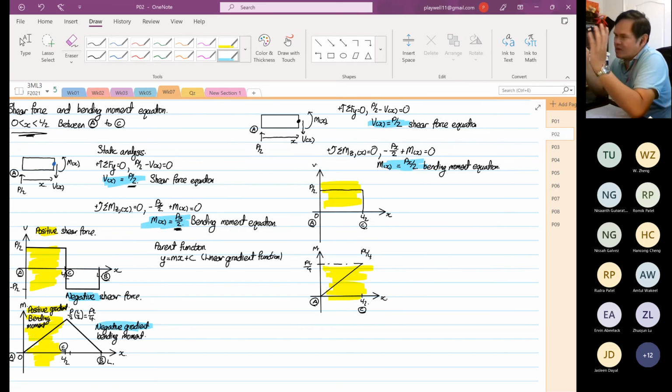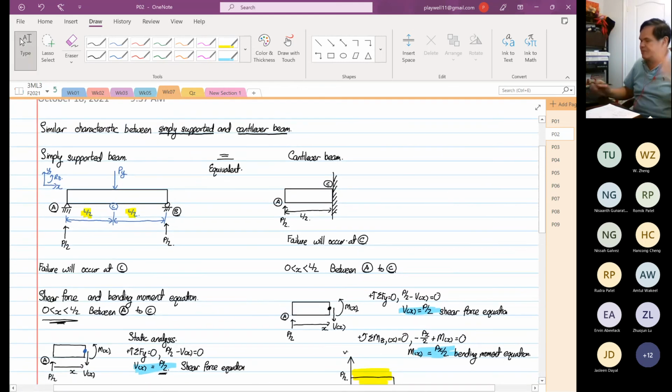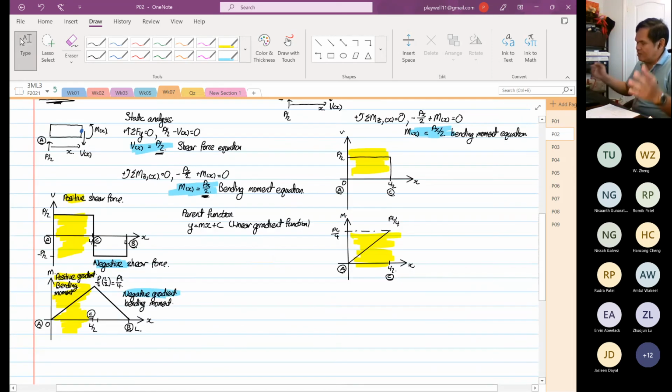If now the equations are different, then we cannot say that the simply supported beam that has a load in the center is the same as a cantilever beam where the load at the other end is P/2. But we have proved this mathematically, so it is valid.